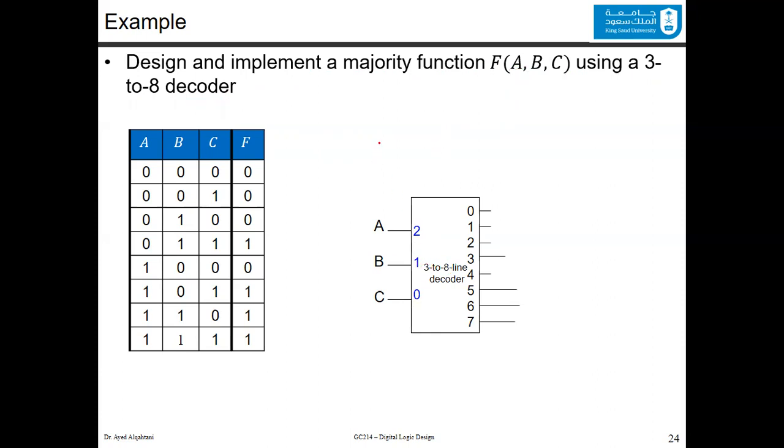Now we know that the truth table, we could construct it for 3 variables this way. And since this function is called the majority function, it's like a voting function, where you count the number of ones against the number of zeros in every row. So here, the 0 wins, here, the 0 wins, here, the 0 wins, here, the number of ones we have is 2, the number of zeros only 1, so the 1s win. Here, the 0 wins, and the last 3, the 1 wins. This is the majority voting function, or simply majority function.